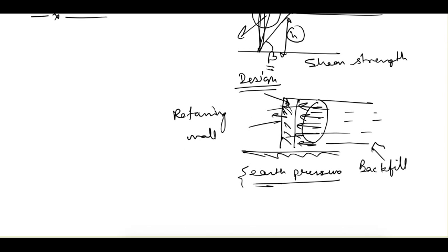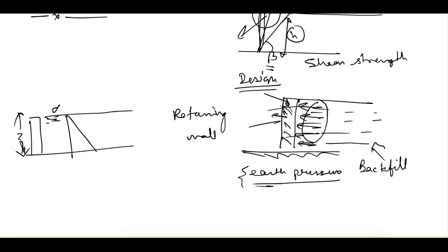But going further into that, let's see what is the difference between soil and water. We know that when we studied vertical stresses, if this is the depth z and the water table is here, the vertical stress on the soil will be equal to gamma dash into z, that is submerged unit weight into depth, and the vertical stress due to water will be equal to q equals gamma w into z, that is simply the unit weight of water times the depth of water.